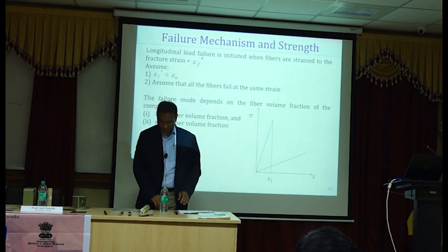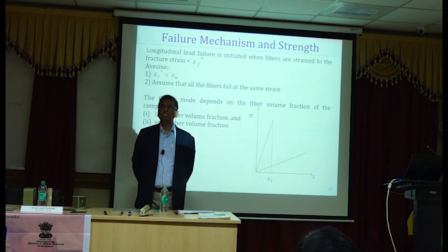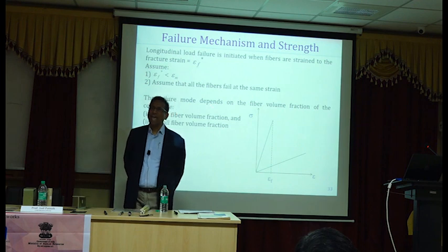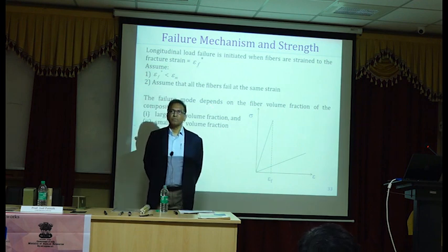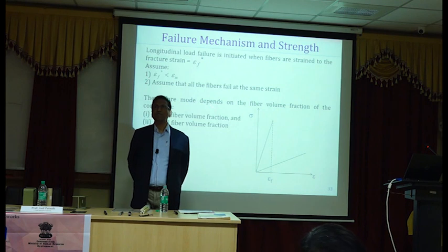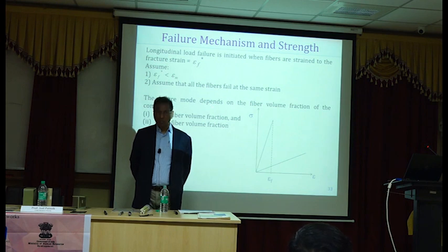Under reinforced is something else, because under reinforced is when you are forcing your steel reinforcement to reach Fy. That's under reinforced, right? But we don't actually provide that. If your steel area from your design calculations works out to be a very, very small area, you still need to provide some amount of steel. And my question is, why?